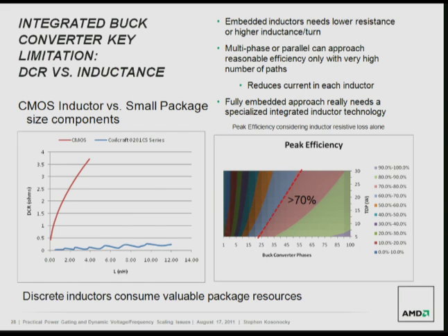If you look at efficiency, if you just look at kind of peak efficiency, where it's gauged by the I²R loss here, to get above 70% for different TDP power levels, you really have to have many parallel regulators or buck converter phases, no matter how implemented, or some combination of the two, to get above that. And it's really looking at 25 or more, or up to even 85 or so in that regime, to get, let's say, 15 watt TDP or 20 watt TDP to make that efficient there. So that's challenging by itself.